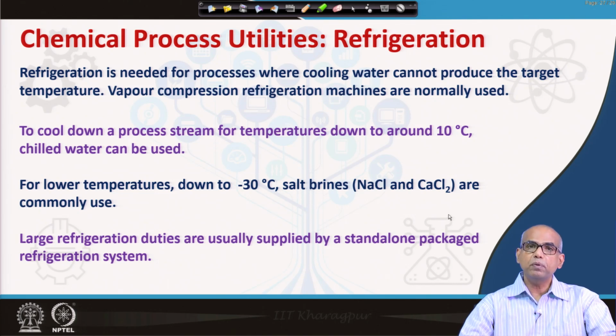So, up to 40 to 50 degrees Celsius, you use cooling water. Up to around 10 degrees Celsius, you can use chilled water. Below that, down to minus 30 degrees Celsius, salt brines can be used. Large refrigeration duties are usually supplied by a standalone package refrigeration system.